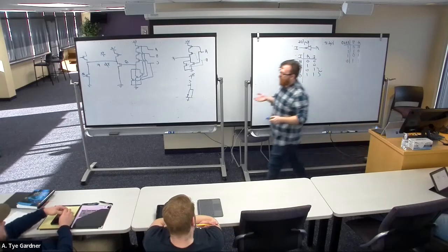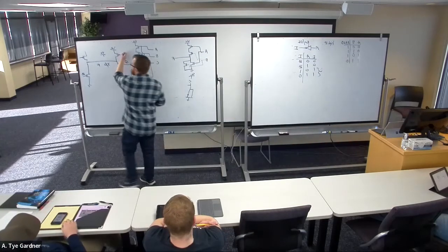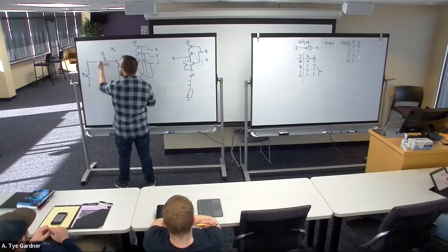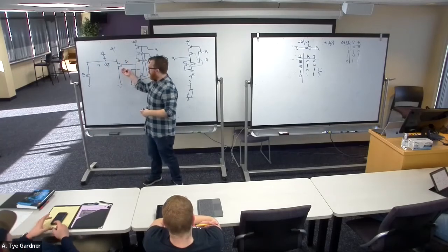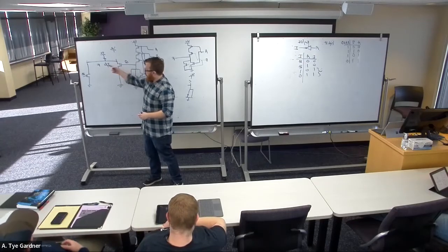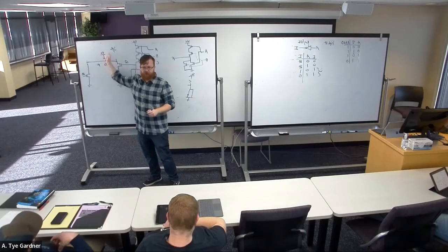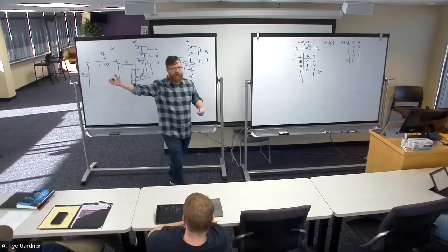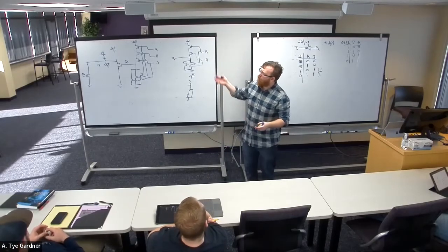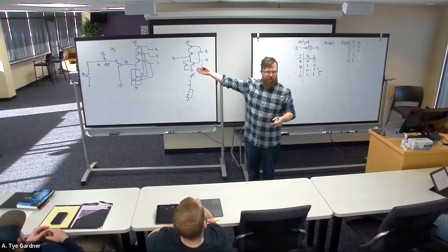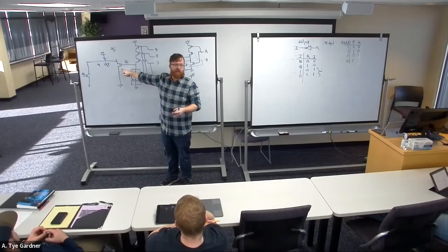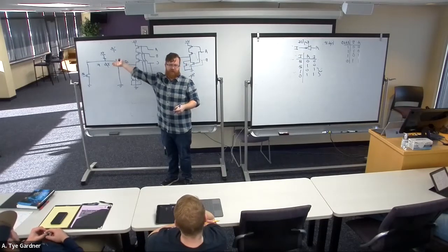But in the case of a resistor, if I make a 0, then current flows. And if I make a 1 and there's input leakage on whatever I plug into, then current flows. So that resistor is going to have a voltage drop over it. So that means I'm never going to quite have 1 out there, am I? I'm going to have 0. This is actually very good at making 0. But I'm not going to have 1 because that resistor has a voltage drop.